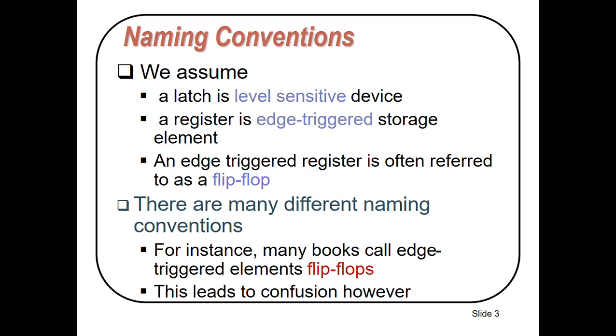So we should discuss the naming conventions here. We assume that a latch is a level sensitive device and a register is an edge triggered storage element. An edge triggered register is also called a flip-flop, but other books can use different conventions. For example, many other books call edge triggered elements flip-flops.